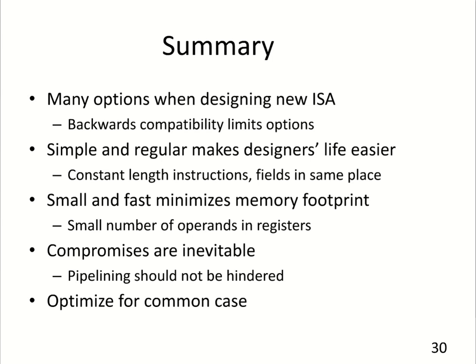And a final guideline to follow, which again derives from Amdahl's law, is to optimize for the common case. So you don't want to add a new instruction that requires a lot of changes to either your software or to your hardware if in fact that instruction is expected to be used very rarely. You should optimize for the kinds of operations that are commonly performed and that are the common case.